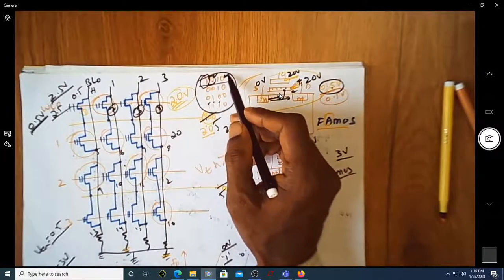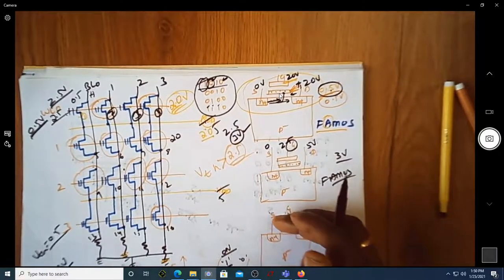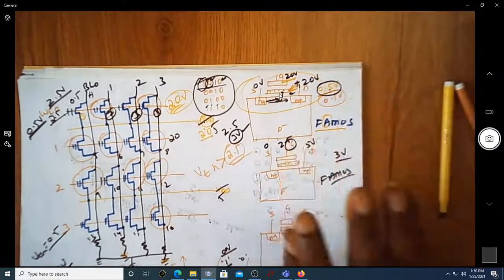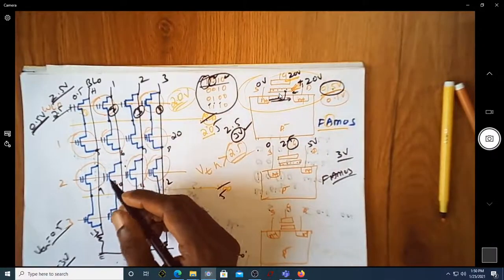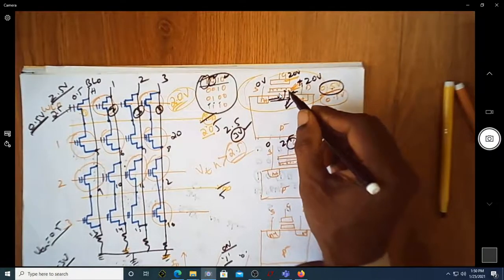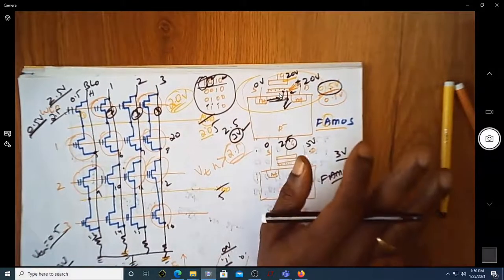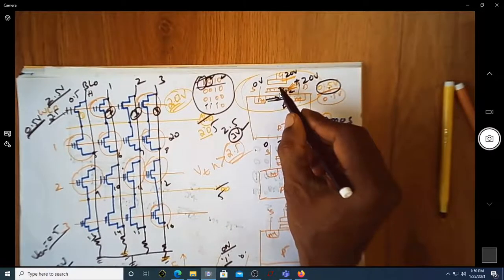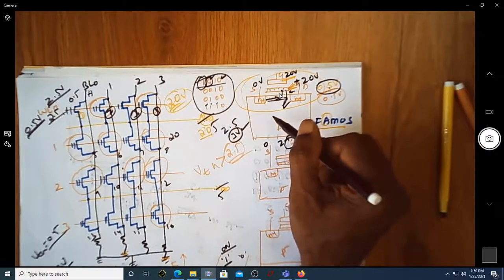In such a case we are actually storing these values of ones and zeros. So assume that I want to reuse this for some other application. Next, what I have to do is take out all the charges that are there in this particular transistor wherever the threshold voltage is enhanced. The charges which are trapped in these gates can be moved down to the substrate by exposing this entire structure to UV light. Under ultraviolet rays with sufficient intensity, these electrons can be released and they can go back to the substrate.